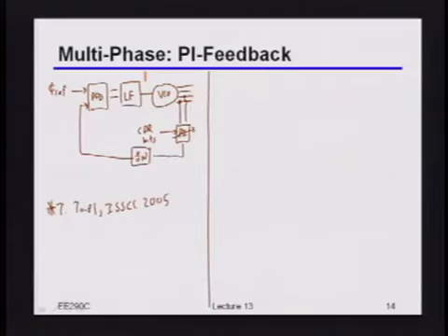So, I mean, ideally, the phase should be locked to like quadrature or something. Or depending on the lock point, you can probably change, insert some offset into the comparison between the two phases. Okay, you could do that.